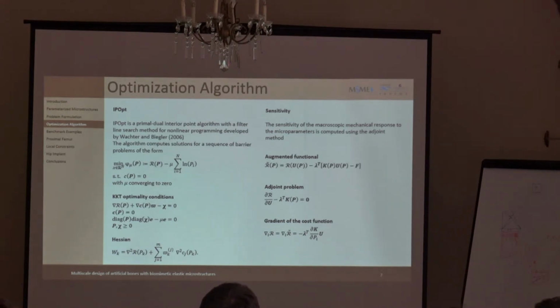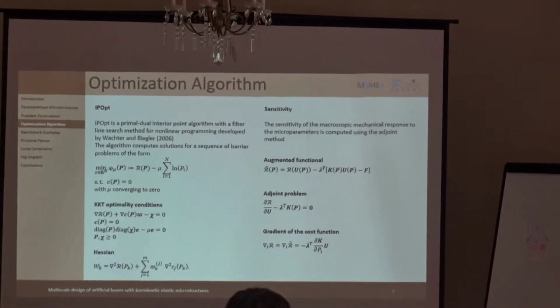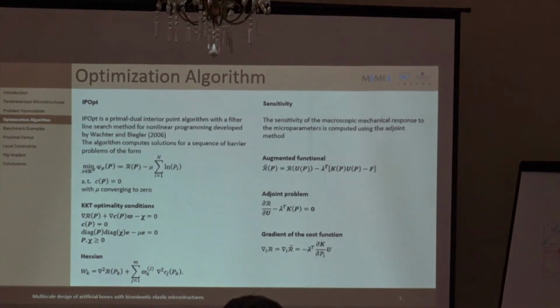It is actually a much faster method than the direct method to compute the derivatives, because it only uses one back substitution to solve the equations, at difference with the direct method that uses a large number of back substitutions that is directly related with the size of the problem.